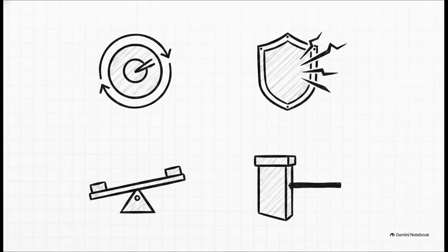And feedback doesn't just fix errors either. It meticulously controls stability, making sure the machine operates safely without erratic jumps. It can modify the overall gain, cranking it up or dialing it down depending on the frequency. And it drastically reduces sensitivity. That means if internal components wear down over time or parameters shift, the system self-corrects and remains practically unfazed.